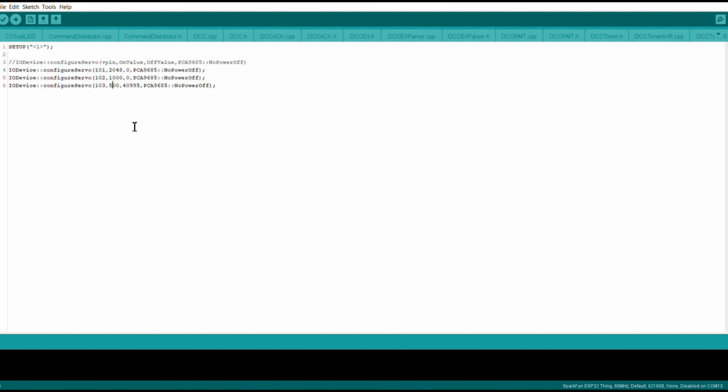So you can do that. Maybe you've got something where you've got lights that alternate. You turn one on and off. You could do it at the same time, just inverting the commands. And let's get the digits right, so 4095 is the full brightness. Okay? So you can change that around. You can do different things on what you want LEDs to do. That is how you define LEDs. You do it in the My Setup, and there's the command to do so. But again, if you're just using on and off with full brightness, or you want to use the fade command to control the brightness, you don't have to define them at all.